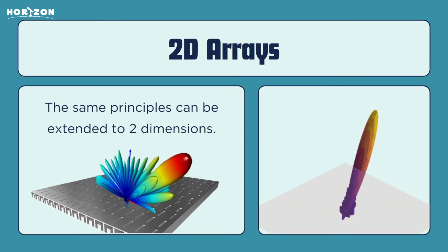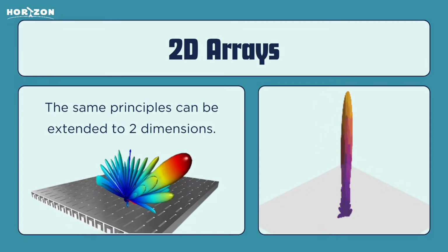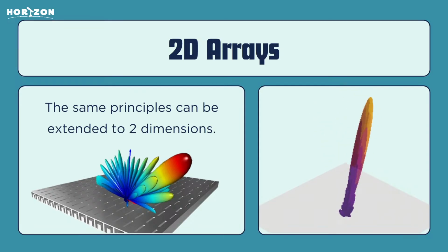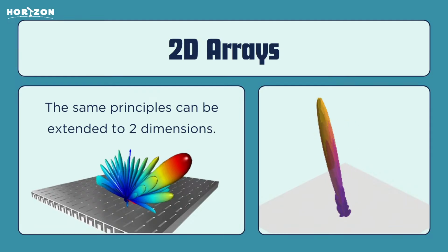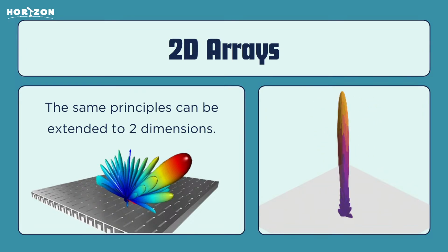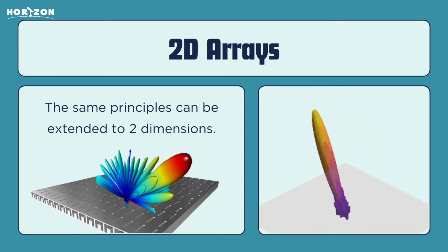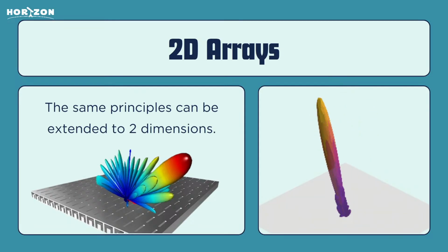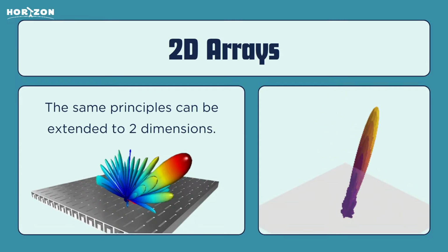So in this way, we can use a multitude of simple antennas to create a complex radiation pattern, which can be used for looking into one part of our environment or one part of our night sky, for example, with very high accuracy and very high directivity, yielding a very good result. Usually you would see that instead of creating a very huge antenna, a lot of modern antenna systems are an array of antennas. They are all separate antennas spread out over a huge piece of land, and we can do interferometry or such antenna array techniques with them.